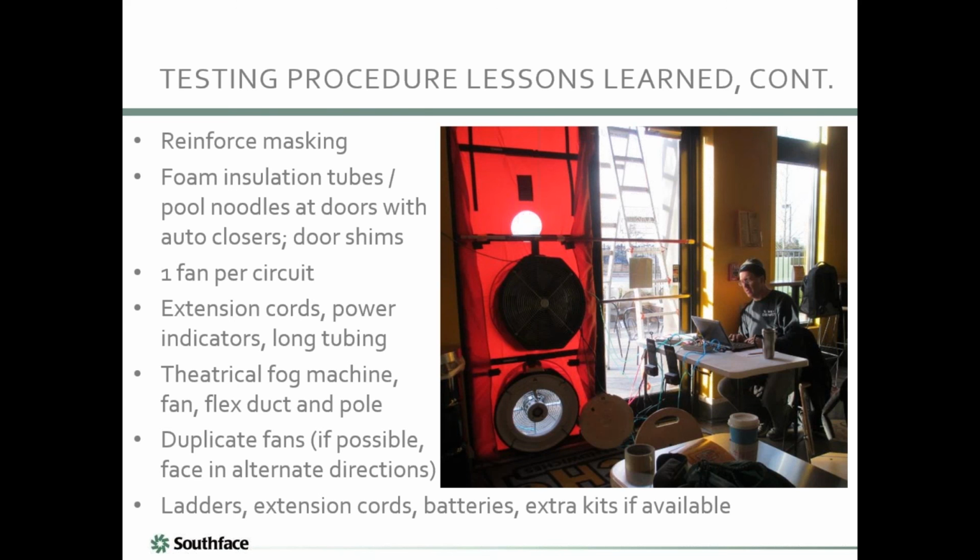So these are approximate numbers. I believe you might be on, say, a 20-amp circuit, and a blower door on high speed might be 9 amps. And so you're like, well, 2 of those, that's less than 20. And you're right, you can actually sometimes do that and get it to work. But when you throttle back on a blower door, because of magic electrical losses, it actually draws power factor. It might draw 11 amps when you're trying to run at half speed. So that will and has tripped a breaker when you're running more than one fan.